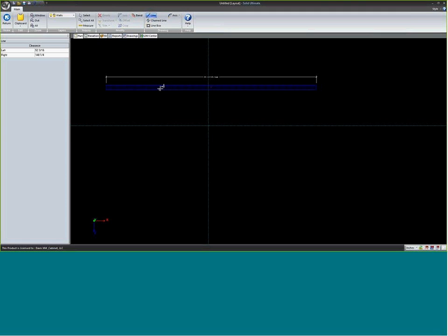What it's asking me is, where do I want this wall in relation to the wall it's attached to? So I'm going to call it 60 inches there on the left. Now it's over to 60 inches. Now I can drag that out and put my T-wall in.